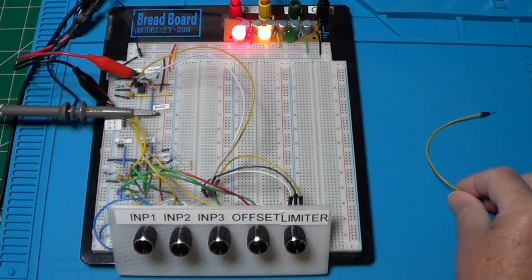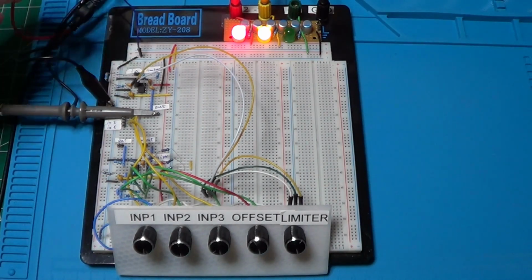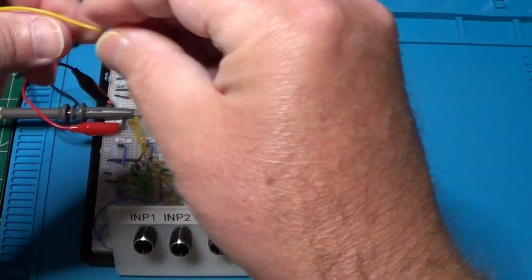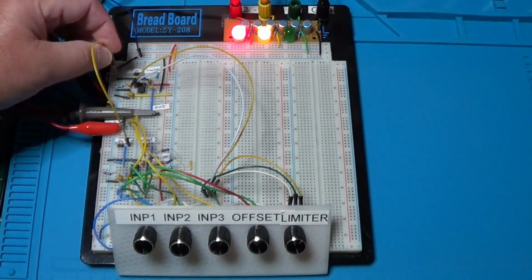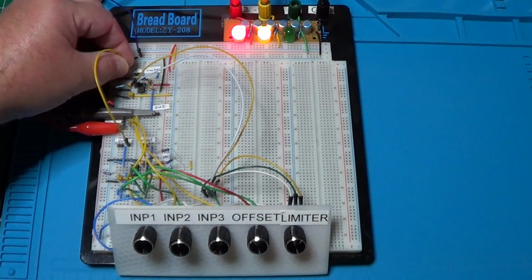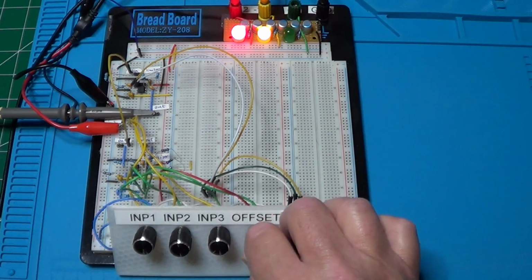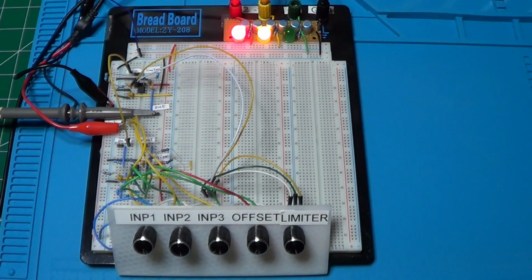Let's now take a look at how the limitator works along with the DC mixer. In particular, we can see the behavior of the signal once we cascade the two circuits together. To do so, we need to move the output of the signal generator from the limitator input to one of the DC mixer's inputs, in this case input 1. The output of the DC mixer will go instead to the input of the limitator. The oscilloscope will still be connected to the limitator output.